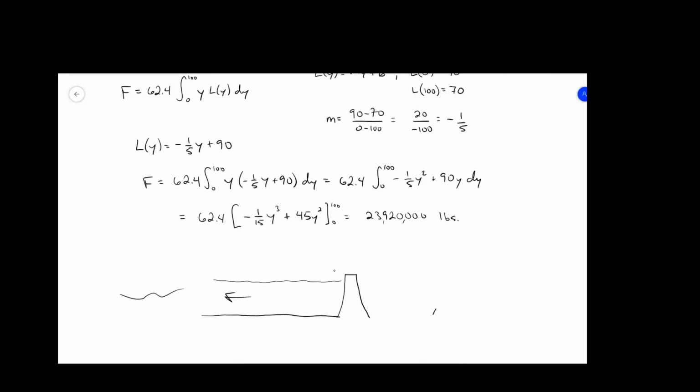maybe a situation like this? Maybe I have a dam like this, and I only have a tiny little bit of water. So suppose I have a wall right here, and I just have a little bit of water right here. Does it make a difference? Suppose these dams are identical in every other way. Does it make a difference the force that's being pushed on this dam versus the force that's being pushed on that dam? Only the density matters. That's it. Only the density and the gravity matter. That's it. So no, that's the answer, right?